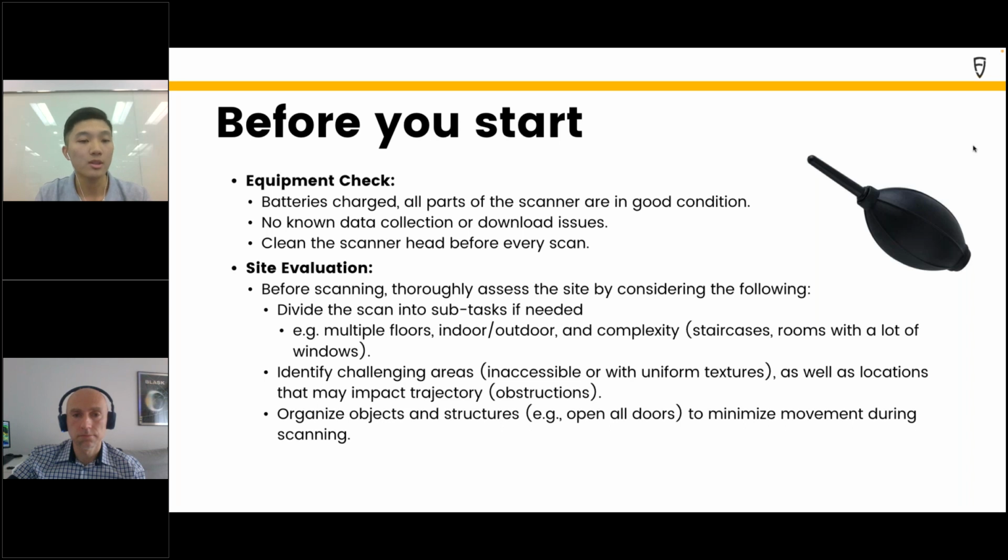Also, take a walk through the site, the scanning area, take notes, and know there could be some challenging areas, and plan your route before you do the scan. It will be helpful for you to mark a physical or digital floor plan if you have access to one of them.